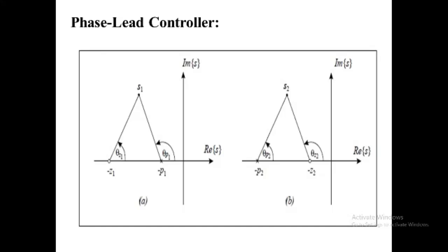And so their mutual contributions to the root locus are almost negligible, since the root locus is practically unchanged and the system transient response remains the same. The effect of this PI controller is to increase the type of the control system by one, which improves the steady state error. The effect of a dipole on a particular response is studied next.